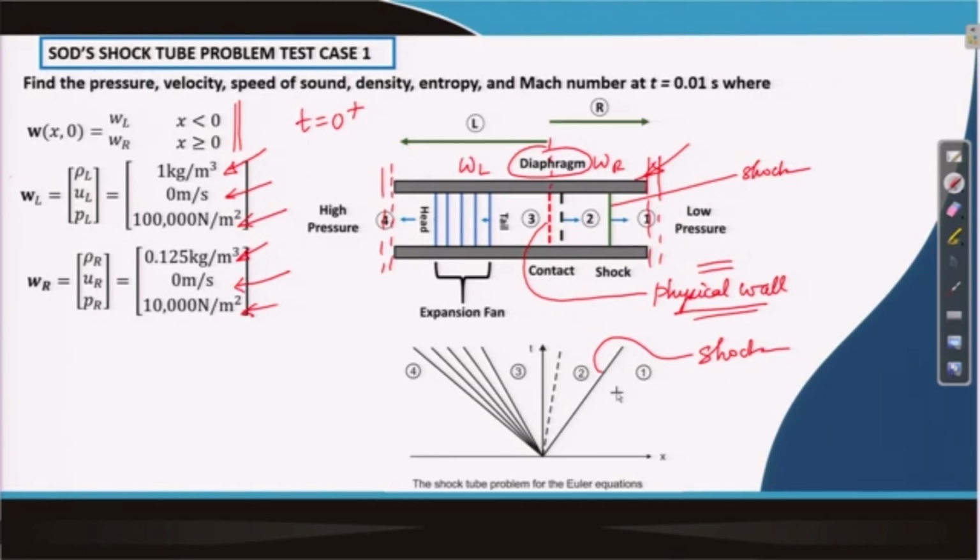And then we find that as the shock runs away towards the right, it pulls with it the flow behind it, and somewhere in that flow there is also a contact discontinuity which is running behind the shock. This contact discontinuity usually can sustain certain jumps across it.